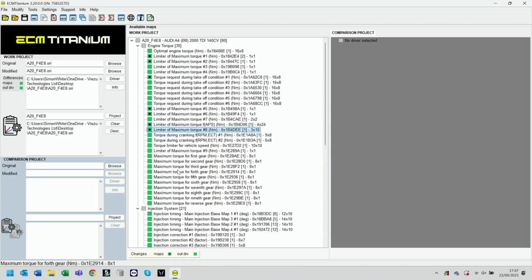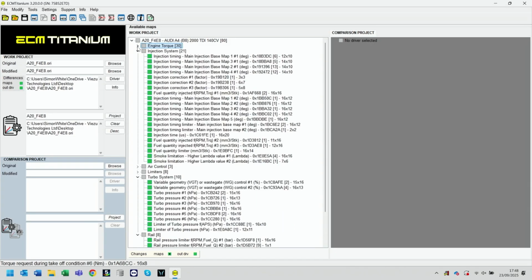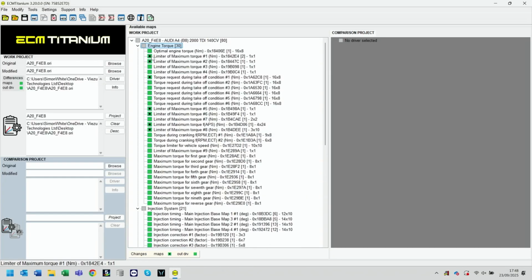So we've changed, what, 5, 6 maps now? We are 7 maps changed. Okay. And that is it for the torque limiters on there. Okay. Everything else we saw really high values. Again, out of 30 maps, we've only modified 7. So we can effectively minimise that area. Okay. It's done. We'll just show you quickly. So you can see the maps you modified with the dot. Very useful, green cell. Yeah. Again, helps you keep track.